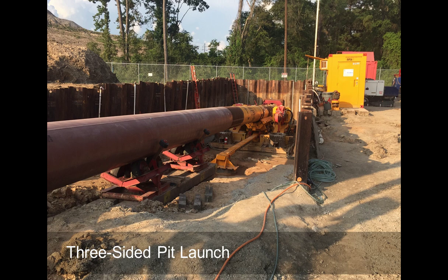This is an example of a 3-sided pit launch. It's a project that we designed in Louisiana, and this is a little earlier on in the equipment setup phase. The thruster clamp's not on, the launch seal's not on, but you can get a feel for how the launch pit setup looked. And we see this pretty commonly in launch setups. Depending on the topography behind the pipe thruster, it can reduce the amount of pipe handling equipment required.